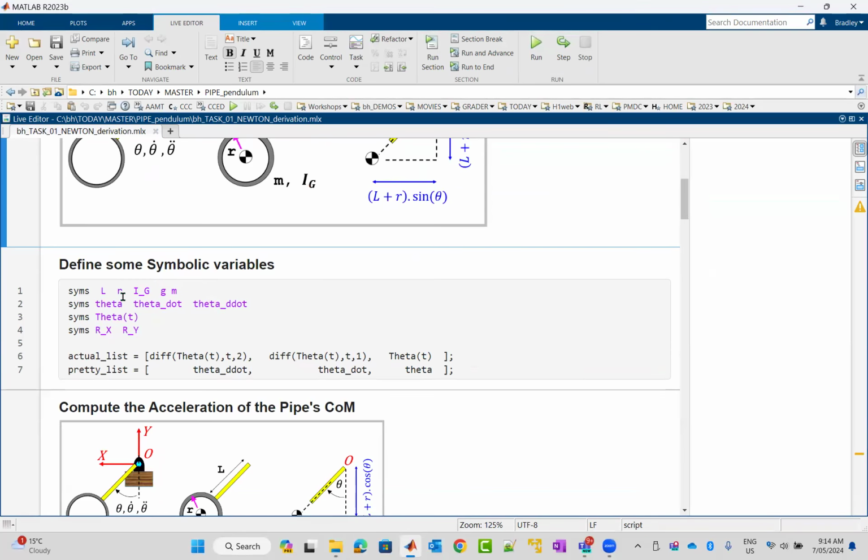And that gives you some visual feedback that this is the currently selected section. Not only does it give you that feedback, but if you click on that blue strip, it will execute just the MATLAB code that is defined in this section. So I'd like you to do that right now. Click on that blue strip and it will execute the MATLAB code of the currently selected section.